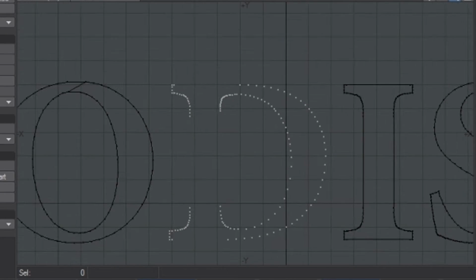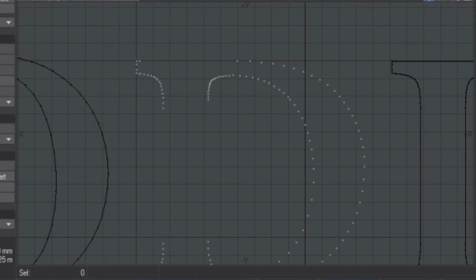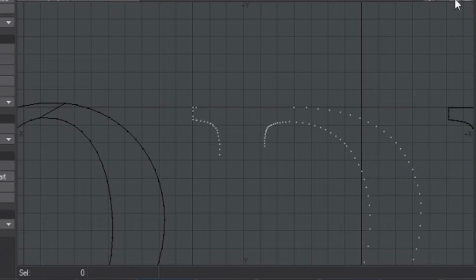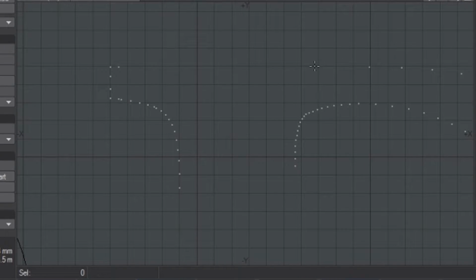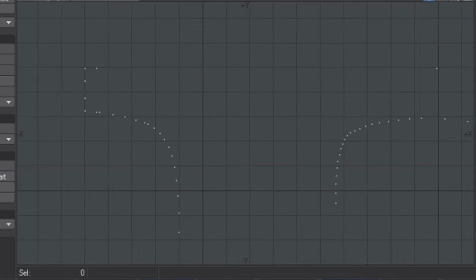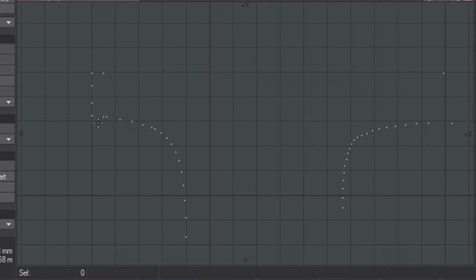And the first thing to know about this is that going to the Make Polygon tool has some issues. One of them is that it's going to try to use all of these points, and we're going to give it a little help because some of these points we obviously don't need. For example, that's a straight line. We don't need 4 points to express that. So what we're going to do is go through and get rid of some of these extra points. Also, if you have points that are very close together, you can just get rid of at least one of them.